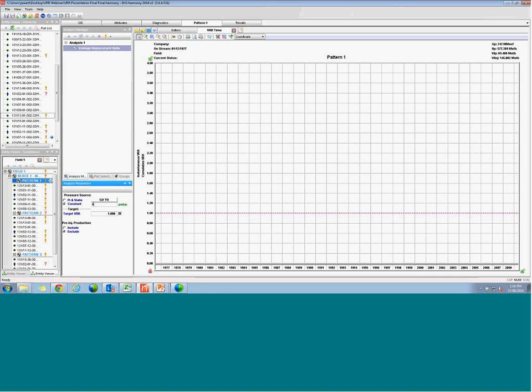I know the reservoir pressure was 5,000 psi. Now let's compare between the two and see what the difference is. There's not much of a difference in this case between these two cases when static pressure was added. But in different cases, by having that static pressure data, it could be a lot different than having constant pressure and therefore constant formation volume factors.